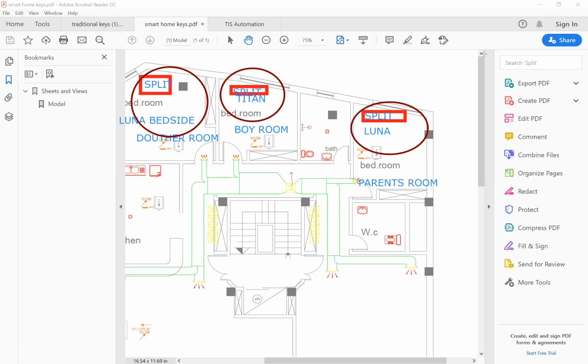Listen to me. The 8 ACs that your Luna can control are not related to the slave. Your Luna can control 8 different ACs. Finished. If you want your Luna to work with the AC of other rooms, and the other rooms have their own AC panel, you can put the subnet ID and device ID of the other room's panel on the Luna. Do you understand?